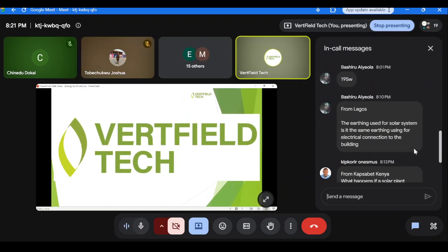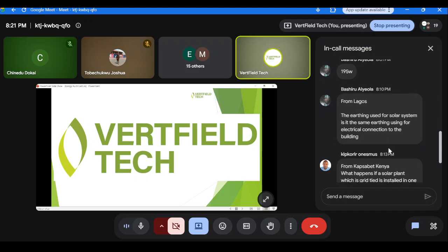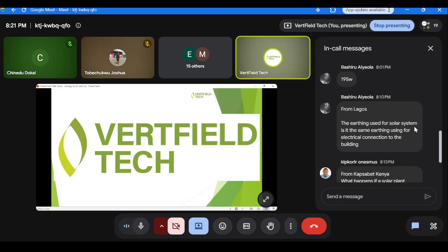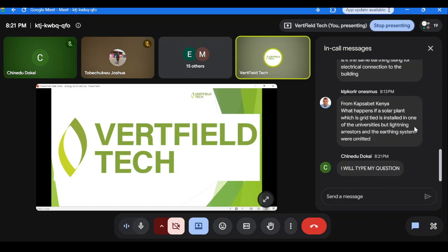Thank you. So Mr. Bashiru from Lagos is asking, the earthing used for solar system, is it the same earthing used for electrical connection to the building? Yes, sir. I think that's what we explained earlier when one of us asked that question on earthing. It's actually the same earthing system, or you can decide to run a new earthing system especially for your solar. It's also good that way.